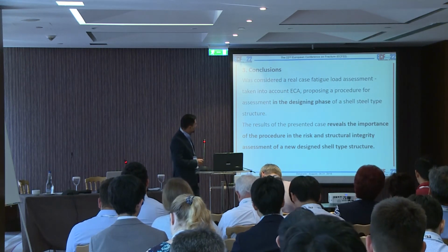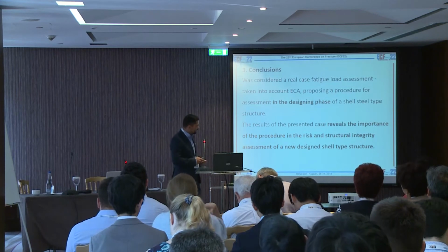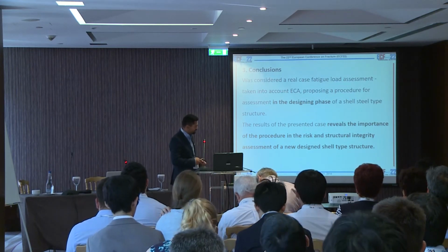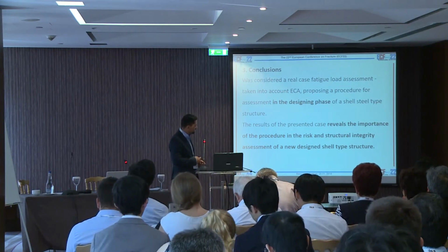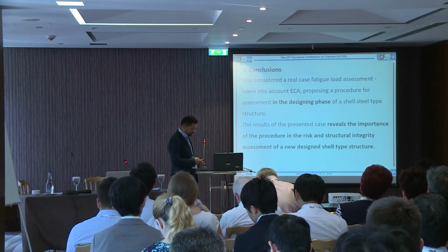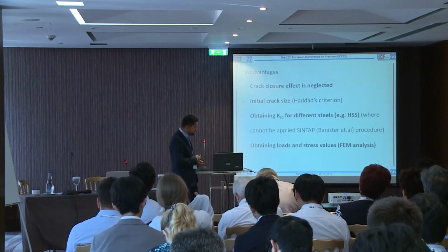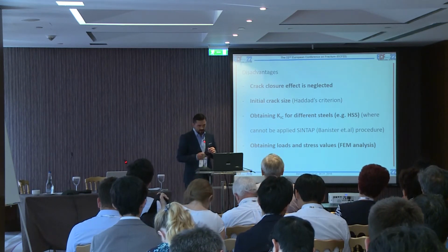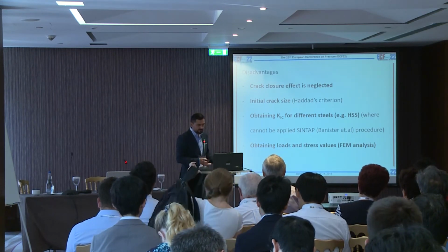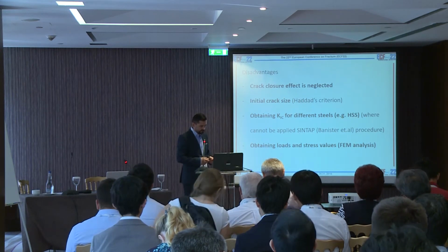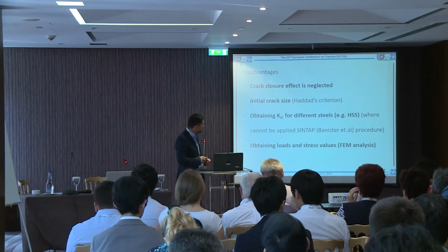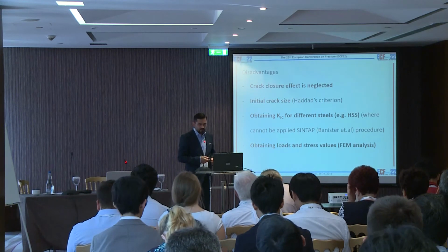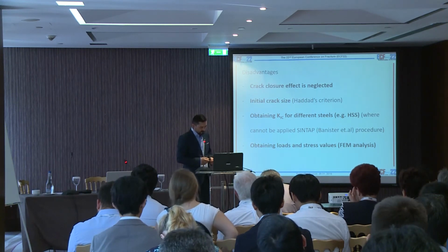And that's all. As a conclusion, the proposal, as I said, is to apply ACA from the design phase, and I will underline some downsides. The crack closure effect is neglected, of course. It's a simple model. This is maybe one of the major problems. For the initial crack size, Haddad's criterion was applied.